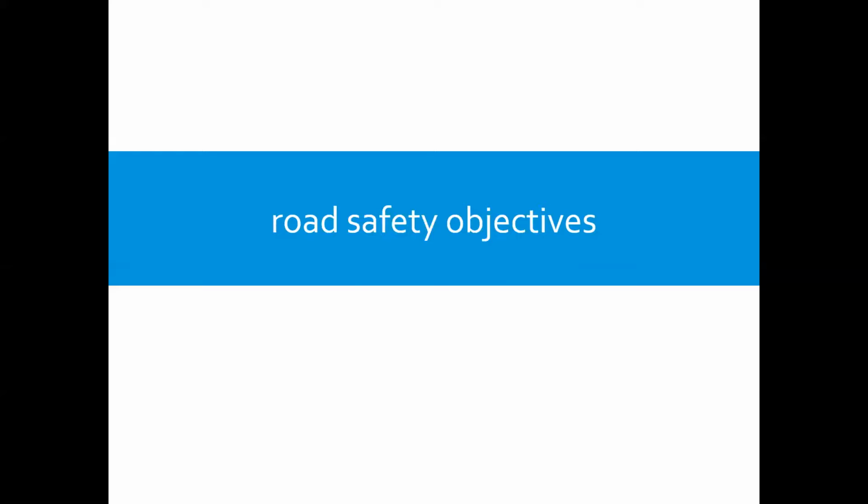We are talking about roads in urban conditions, and we intend to provide a space for cyclists, so the cyclists also need to be considered. Provide a roadside environment that forgives a driver's errant or inappropriate behavior by attention to details, such as the safe placement of roadside furniture and by location and selection of type of traffic barriers.